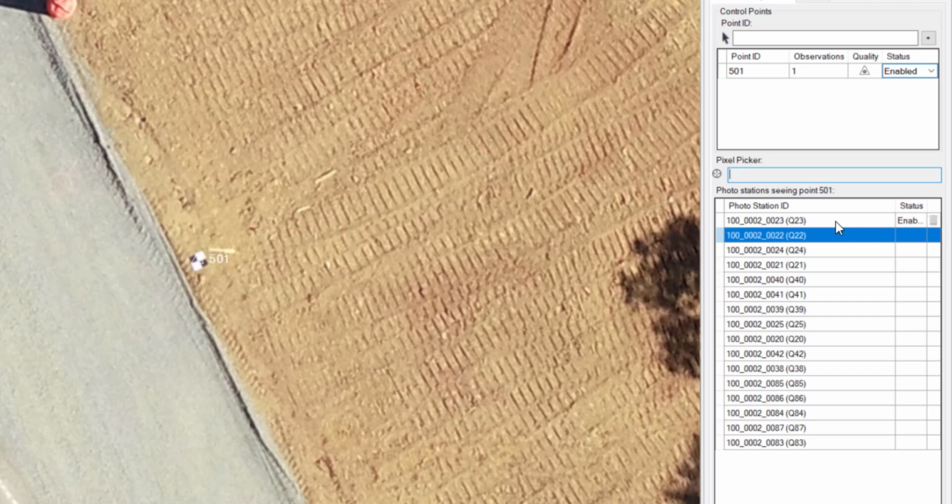So this means this measurement is valid, and then it moves automatically to my next photo, because I have here "automatically advance on pick". If you want to always manually click where you want to go next, then you switch this off. And then just the same part, my pixel picker is active now. I didn't click anything in between. I click in this area, I get here now the magnification, and then I can click to make my measurement.